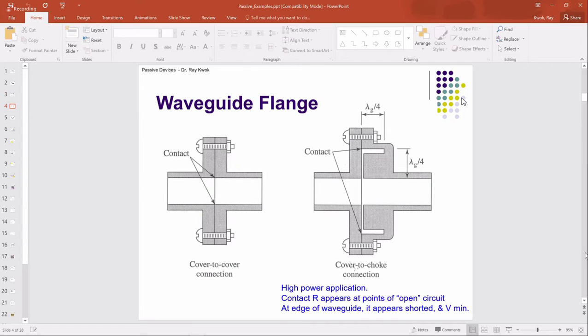The other thing you see people do is on the waveguide flange. So here, let me draw it on. So if I have two pieces of waveguide, rectangular waveguide, let's say, right? It's opening, and the other piece like here. How do I put them together? Well, people make a flange here, put some holes on the metal flange on both sides, and bolt it together like this, right? So these two are the flanges, and bolt it together, right?